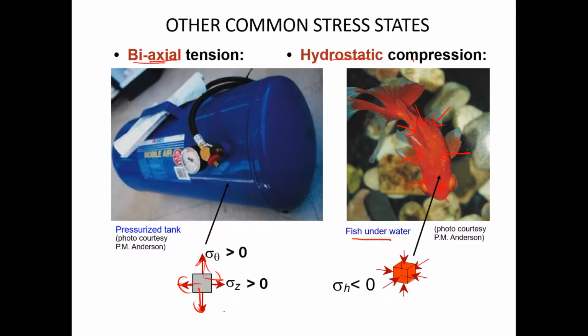Alright, so now we have already learned and discussed the concept of stress and strain. In order for us to study this stress-strain behavior, there are four principal ways, referring to the types of load being applied. Number one, tensile, which is sigma equal to F over A naught.